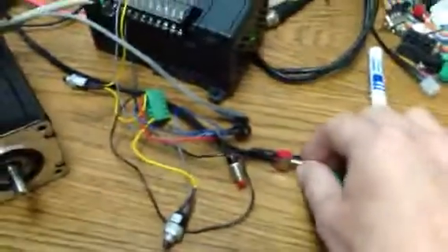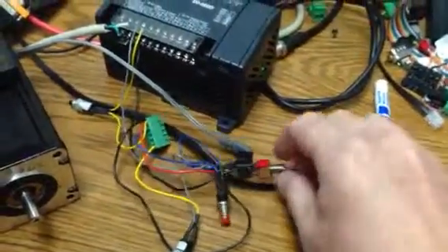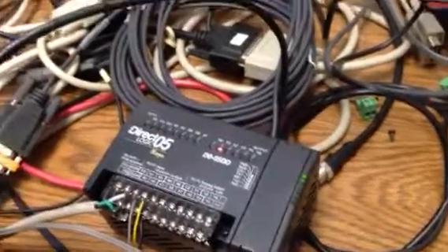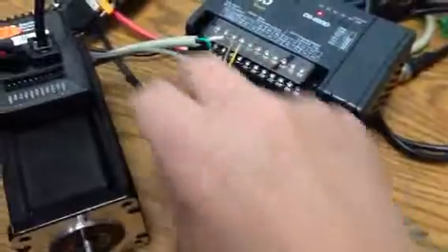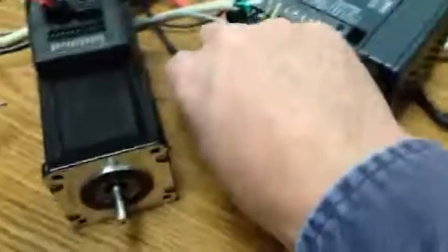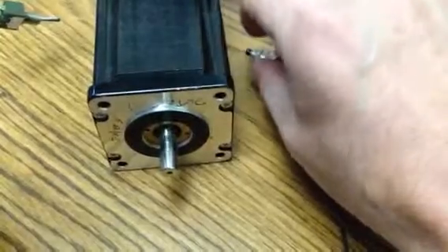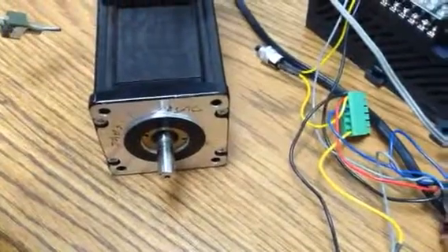STM24 is up. So here is the switch X2, so that will transfer the move parameters. You'll see some LEDs change when that happens. No Modbus error, that's a good thing. And here is the X1 push button, and we should see some motion when I press that. Yeah, baby. Modbus 101.